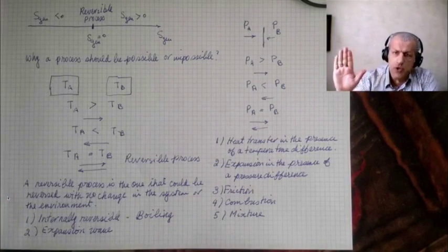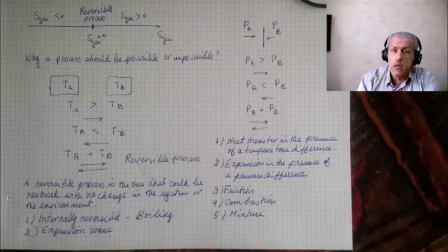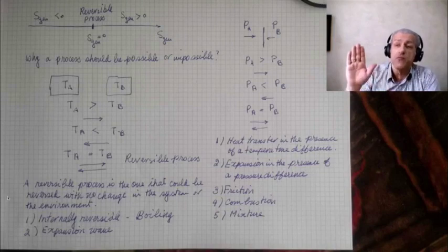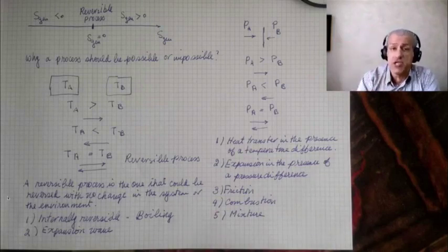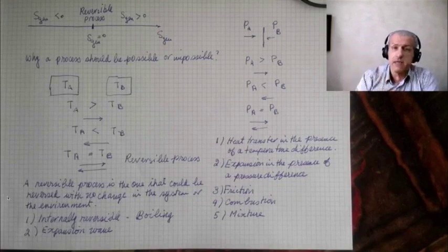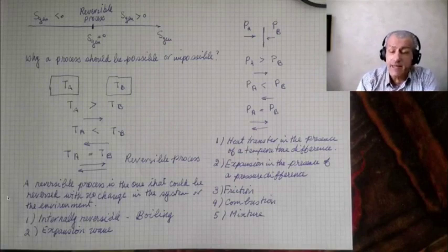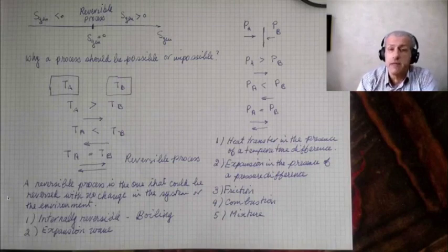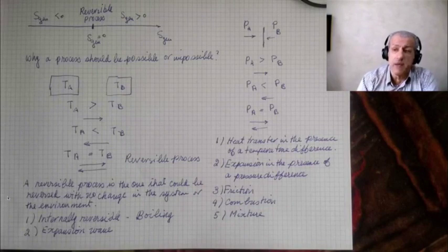You see, when I push my hand forward, I make one compression wave. That compression wave moves forward and becomes a step change, becomes irreversible, even if I push my hand very gently. If I pull my hand back, I produce one expansion wave, and that expansion wave gradually becomes a longer wave and remains reversible, remains with very, very gradual steps.